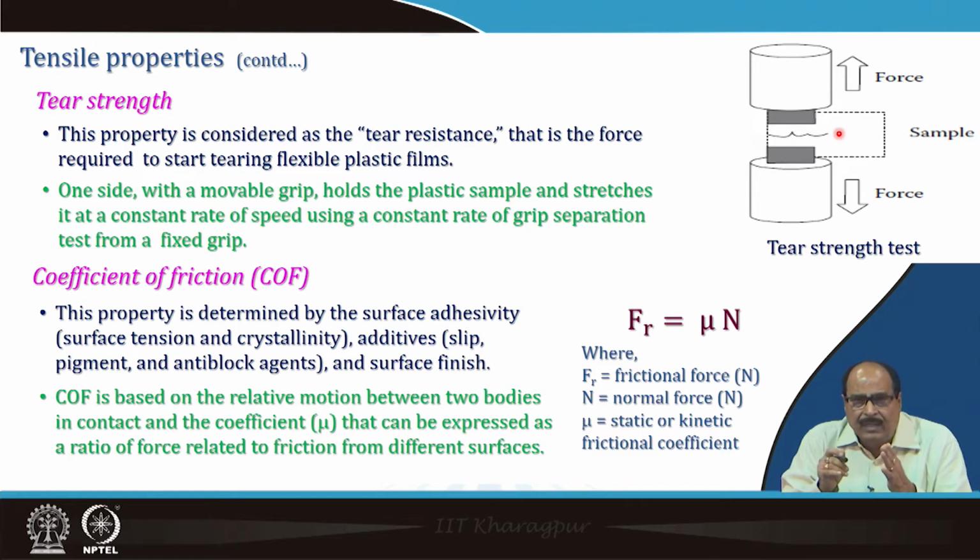The coefficient of friction, this property is determined by the surface adhesivity, that is the surface tension and crystallinity, or additives which may be slip, pigment and anti-block agents, and surface finish.